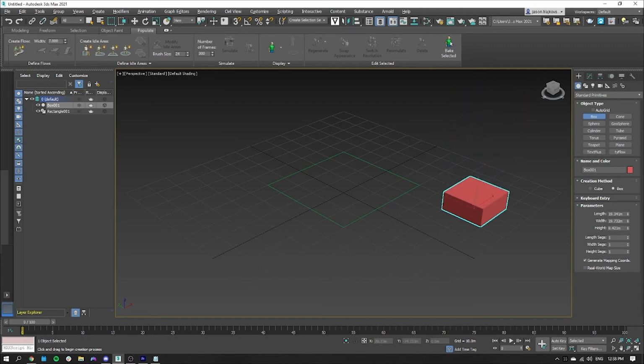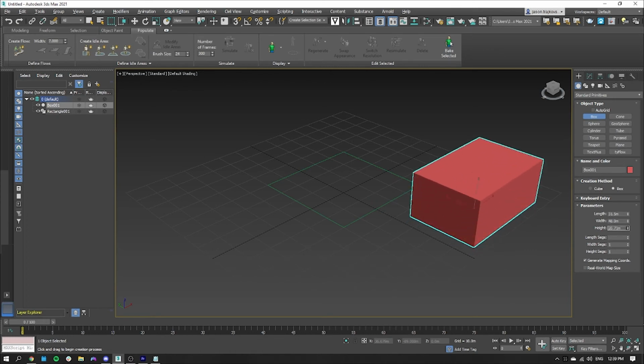You can click on that, or you can just drag across to your parameters here and adjust it. So if I want to go 25 meters in length and say 50 meters in width, that could change that there. You have the freedom in customizing any sort of parameter that is available for easier access there on the right hand side. If you've messed it up and you wanted to quickly alter it, this would be good later on if you needed to adjust your building height, or depending on what your project was, you wanted to adjust the size, this is where you could quickly do it.